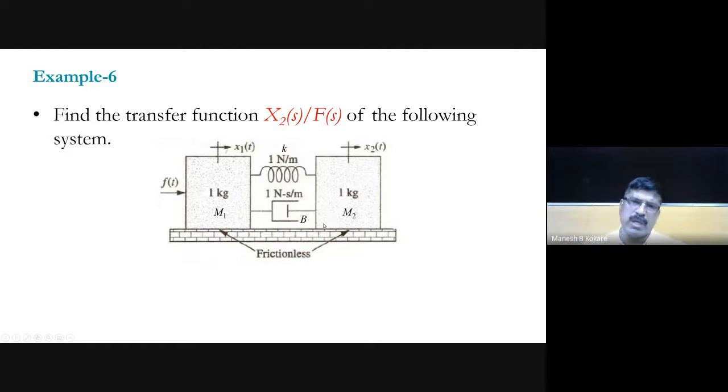So what we will do here, first we will draw the nodal diagram, and then after that we'll write the force equilibrium equations. And once you write the force equilibrium equations, the next step is to find the transfer function X2(s) by F(s).